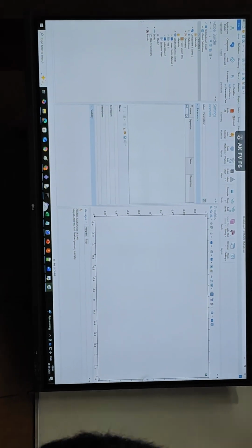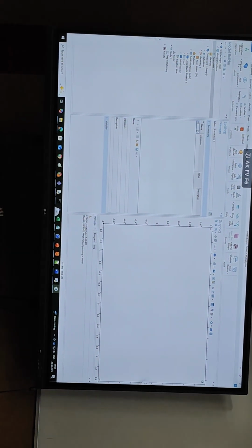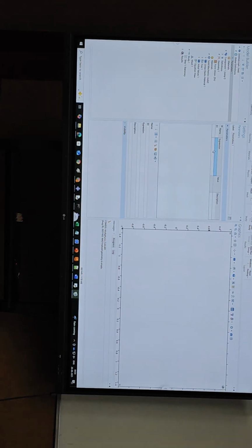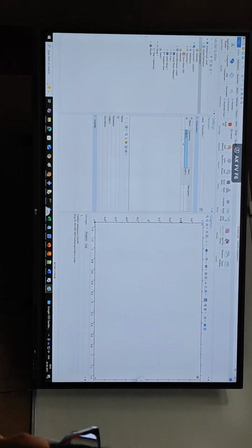So basically then B into T will be A, right? So I'll write it as B rather than A so it will not be confusing. So B1, I'll take a number here, let's say 0.06, and in the parameters you can explicitly define a unit by putting square brackets and writing meters. When I click enter, it will now be defined as meter. If you don't explicitly define the unit, it's non-dimensioned, and so when you use it in the GUI, it will take whatever dimension is associated with that line, which I'll show you ahead.